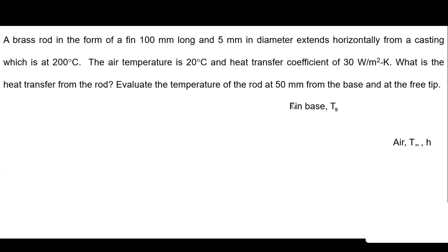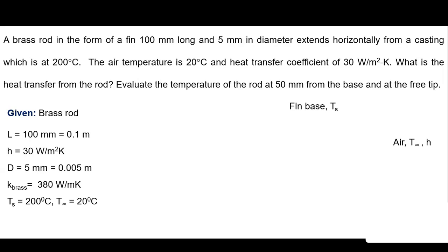Evaluate the temperature of the rod 50 millimeter from the base and at the free tip. Now the length is already known, 100 millimeter, and it's not too long. So we can safely assume that the fin is with insulated tip and we can solve this problem. Identification of our understanding gives us that the length is not so large, so we can use the fin with insulated tip assumption in this problem.